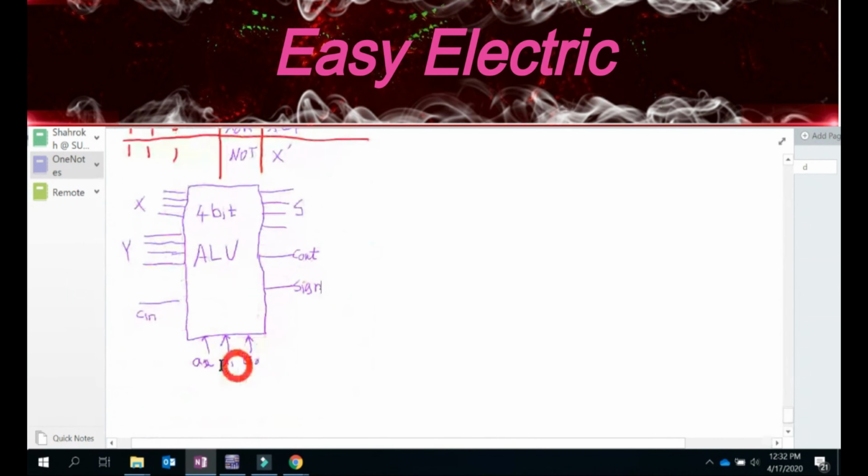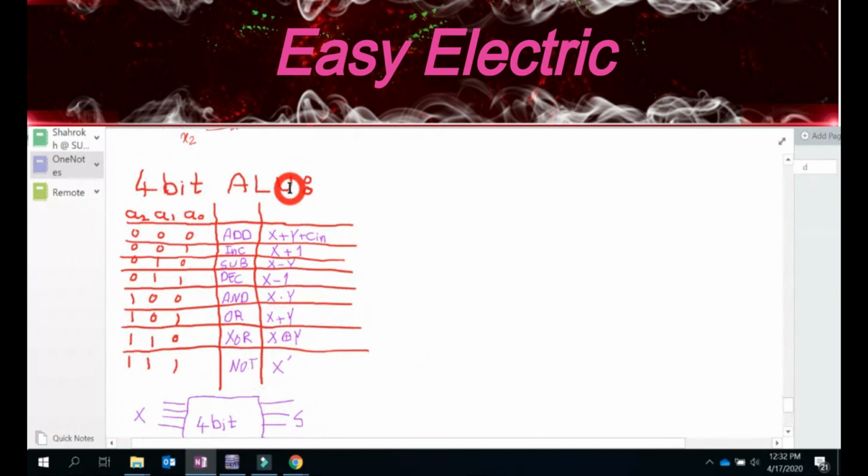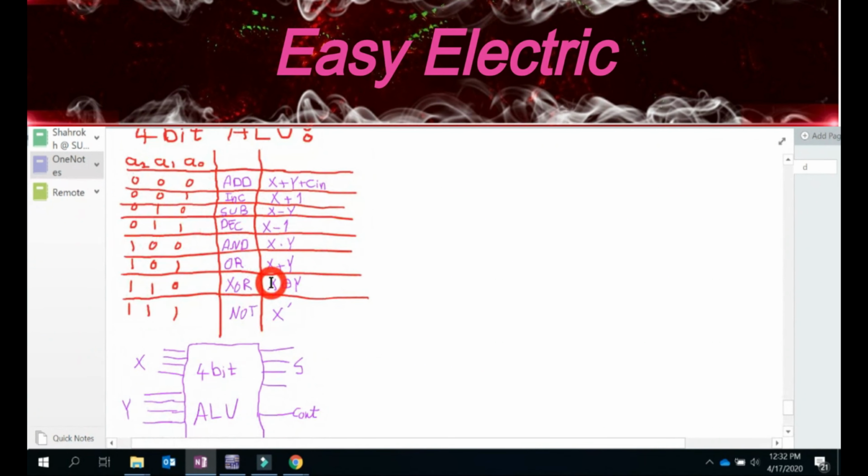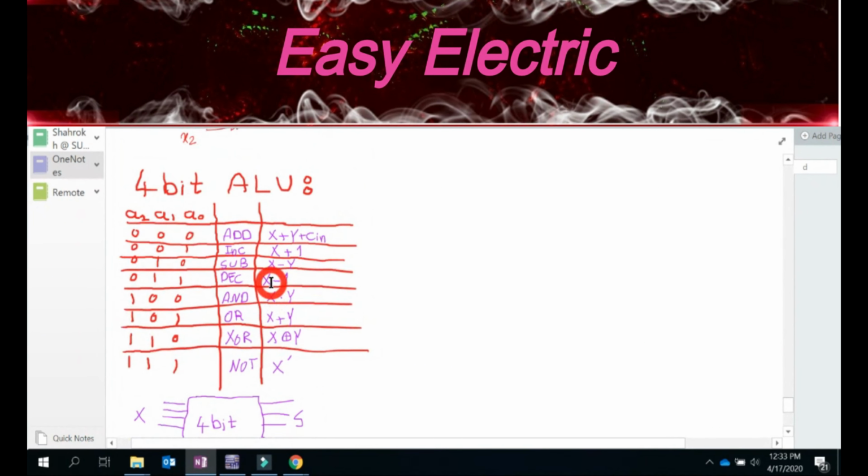Okay, so I want to design one unit, which in the general case has 9 plus 1, 2, 3, which is 12 inputs, and 4 plus 2, 6 outputs. So inside this unit, based off these 3 inputs, you could do all the arithmetic and logic operations, which is generally called the ALU. So this 4-bit one is very basic, but the complex ALU still follows the same design rules. If you understand the basic one, the complex one follows the same concepts.